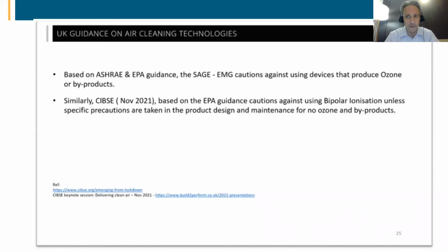This is very important. If you're specifying product, or if you as an owner are installing electronic air cleaning technologies in your building, to be compliant with the recommendations made here by these accredited authorities and agencies, you can go to the Underwriters Laboratories website, and under what they call SPOT, S-P-O-T, you can enter the manufacturer's name of the product.